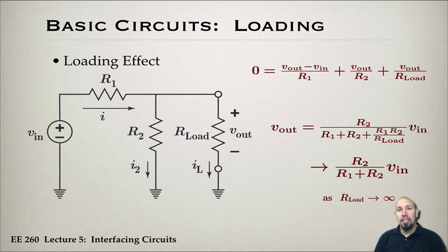Now, fortunately for us, the Arduino circuits have large input impedance. Which means as a load, it counts as very large. It's like 100 mega ohms. So 100 million ohms. That's a lot of ohms. So in that situation, it's practically as if the load resistance were infinite. Okay, so that is a good situation.